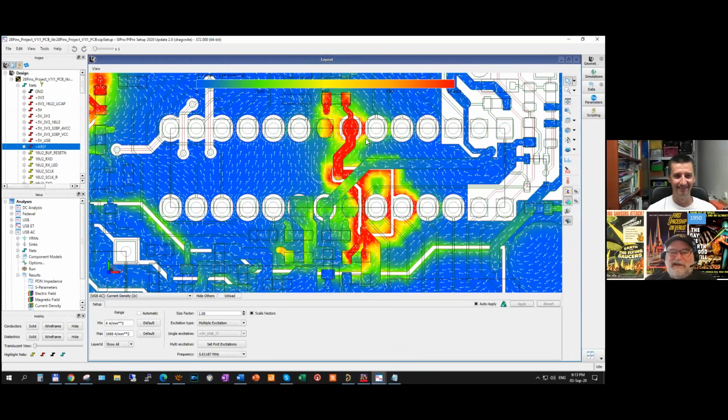And I gave a keynote talk at Altium Live a couple of years ago about how signal integrity lives in the white space on a schematic. The schematic tells you nothing about signal integrity, which is so much based in the return currents. So you never encounter this concept if you're just doing schematics, because it doesn't tell you where the currents are flowing. And when you translate the schematic into a layout, if you don't know where return currents flow, you would never know why to worry about controlling the return currents as carefully as the signal currents.